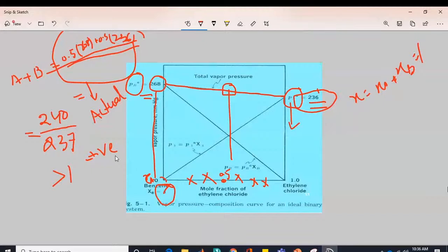So what happens? I'm just giving you an example. Let's say I have a mixture of five different components: C5, C6, C7, C8, C9. So these are some of the components. What I have done is I have heated this mixture up to a temperature of 80 degrees C. Just an example, right? Now, C5 boiling point is 50, C6 boiling point is 60, and I have given a gradient of 10 degrees, so maybe up to 100 degrees centigrade for C8 and C9.